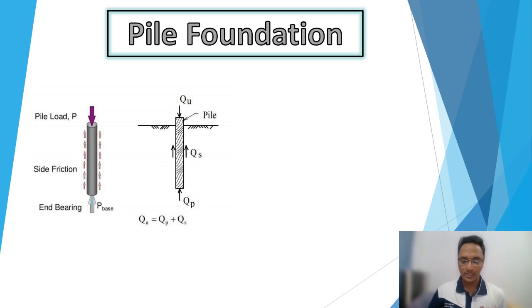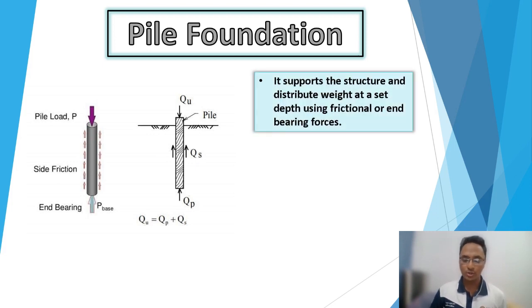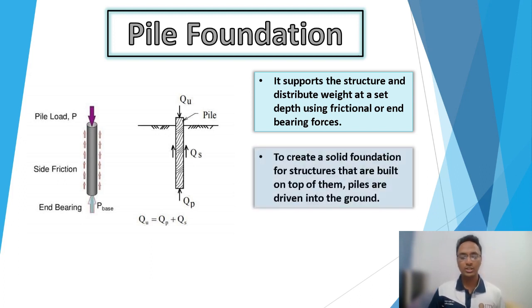What is a pile foundation? The pile foundation is one sort of deep foundation. The pile foundation supports the structure and distributes weight at a set depth using frictional or shaft resistance force or end-bearing forces. Large structures frequently require pile foundations in situations where the shallow depth soil is insufficient to withstand the lateral loads, uplift and other problems.